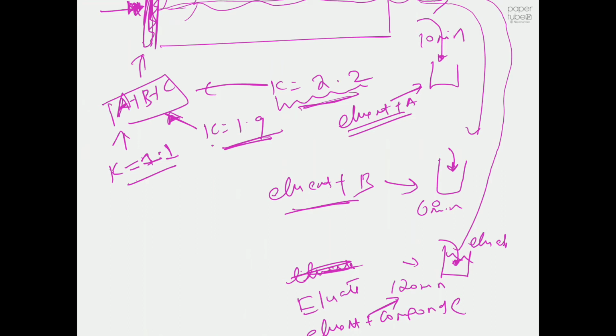We already learned about retention time, the traveling time of each molecule, or the time spent by each molecule in the column, in the stationary phase to be precise. We also learned about adsorption and desorption. It's not a one-time adsorption job; molecules adsorb, then desorb, so there are several equilibrium stages going on throughout the process.